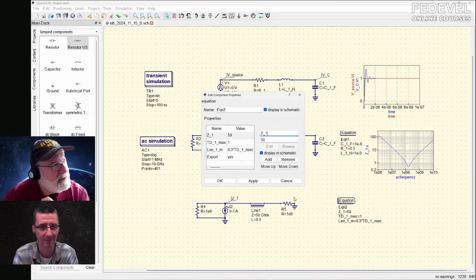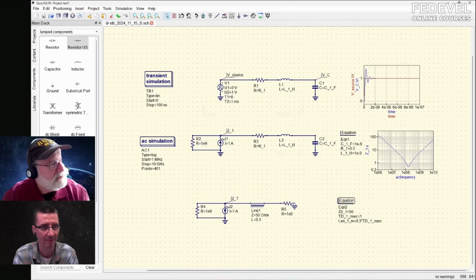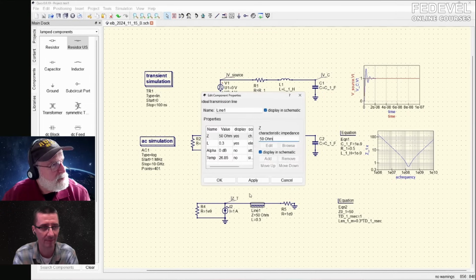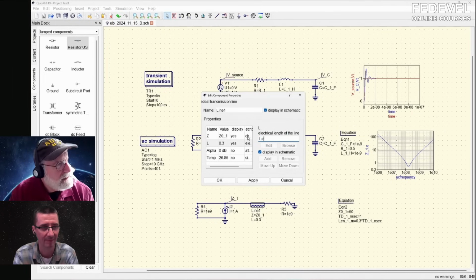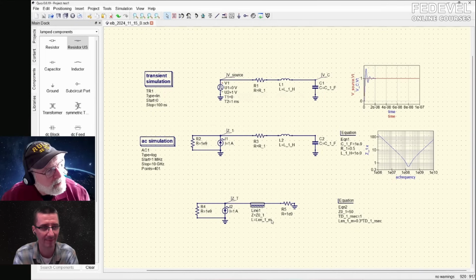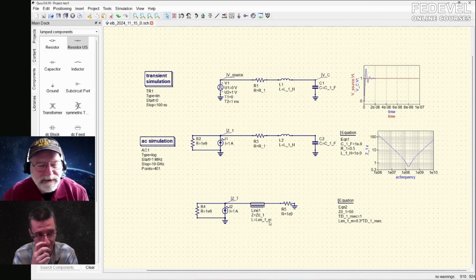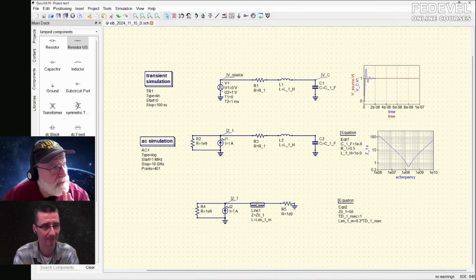And so I'm going to come over here, and you know what I should have done, I'm going to do that now. For characteristic impedance, I like Z0, so I'm just going to readjust the name of that. And now I'm going to put those parameters in here. This is Z0, Z0 for value 1. And the length here is going to be the length of 1 in meters, and I'm going to put that in there. With no units appearing here, we're using the SI unit, so it's meters. So it's the same transmission line that I had before.